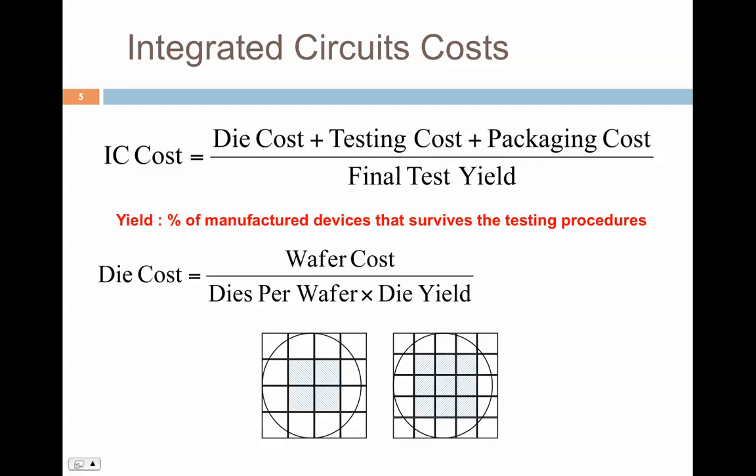Because all the other ones, you cannot use them. Wafers are circular in dimension as opposed to square. So you design the dies to be square, but because of the lithographic process, the wafers are circular in nature. Some of these at the corner get wasted, and the only ones in the center are the working dies.